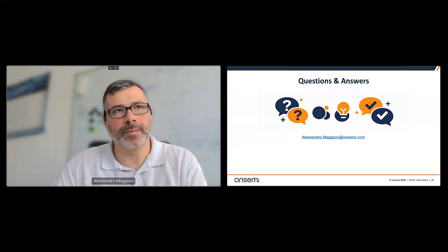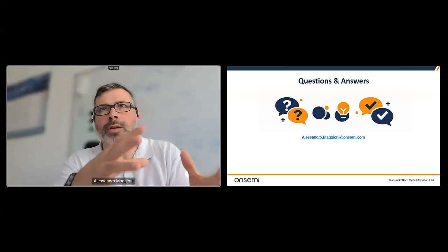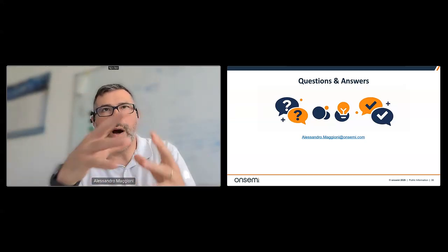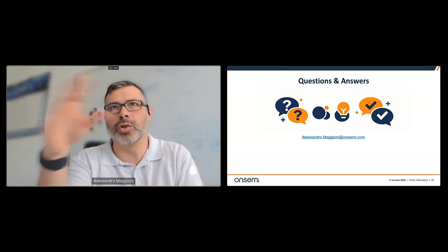Okay, thank you. Graham wants to know, how do the network diagnostics, HDD and SQI Plus, work at a signal level? So basically, the harness defect detection runs in a designated diagnostic mode where one node measures while all the others stay silent.